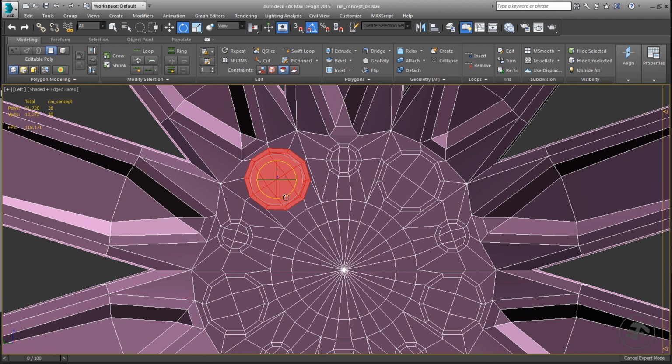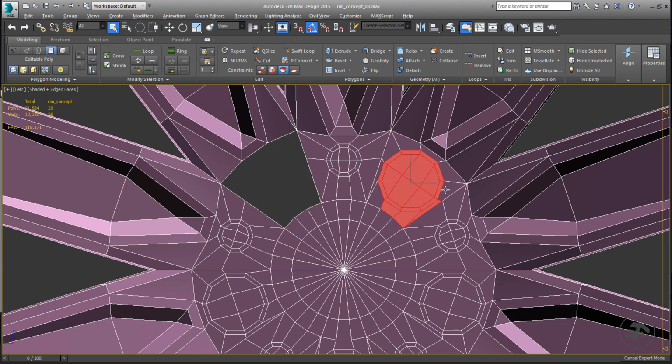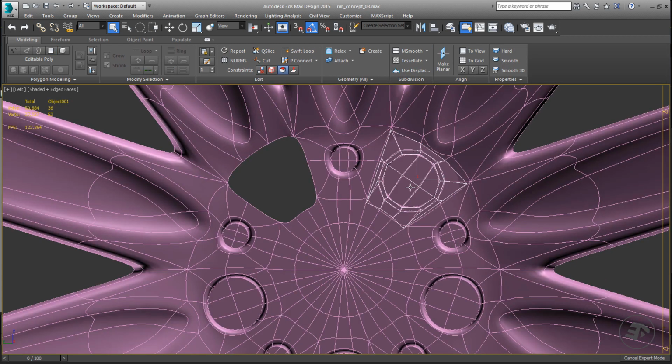In the left viewport, select and delete all the deformed polygons. Select one of the correct, regularized areas. Detach the selection as clone. Select the detached object. On the object level, rotate the object.